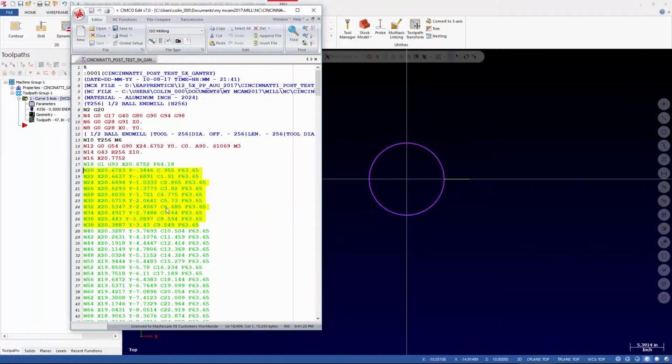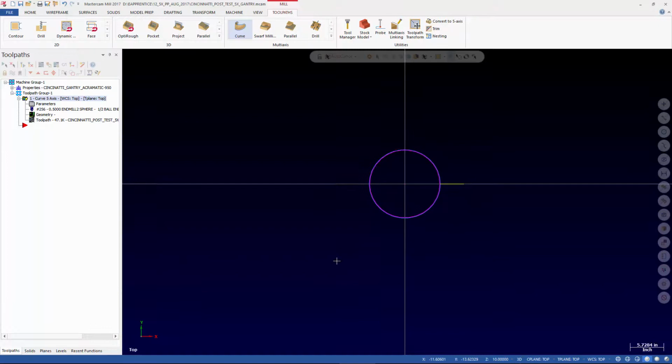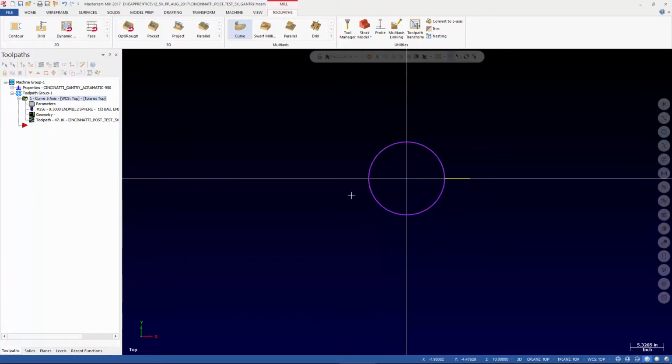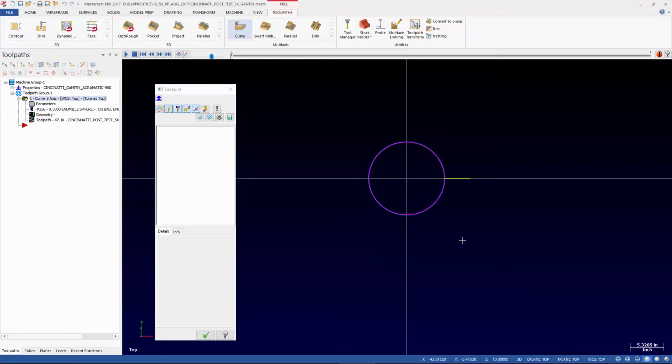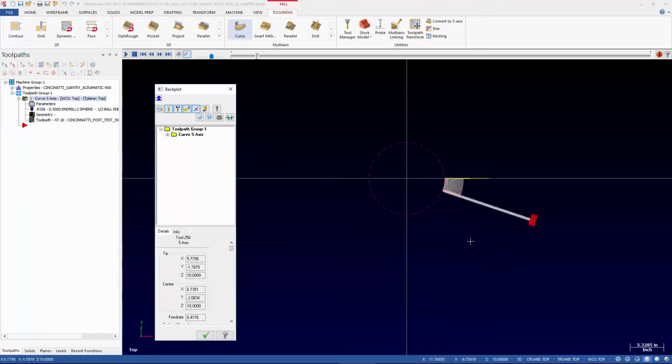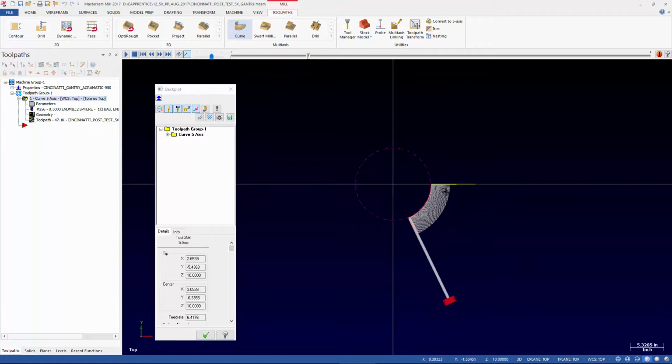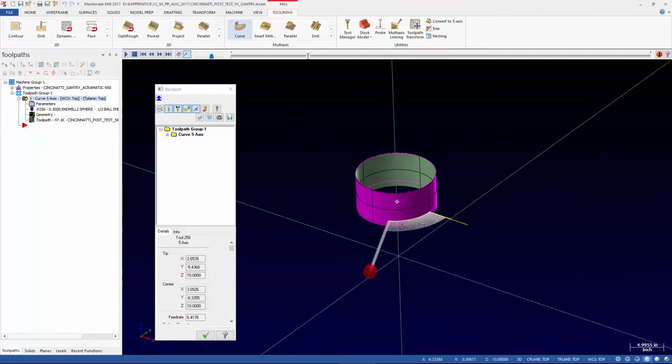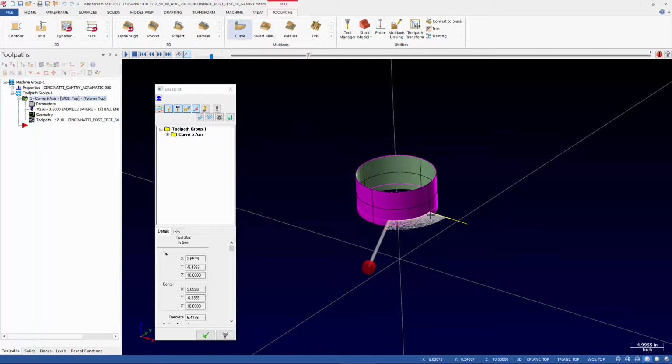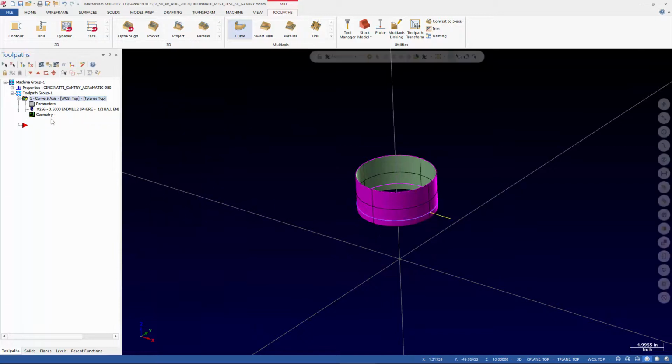Now it goes from negative to positive. But again, I have to make sure that clockwise motion for C on my machine really is positive. Okay, so this is clockwise motion. I'm getting positive C-axis rotation. Now, if this really is positive, but I wanted to cut negative, my post is set up right. I just need to, again, change the geometry.